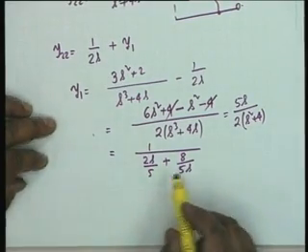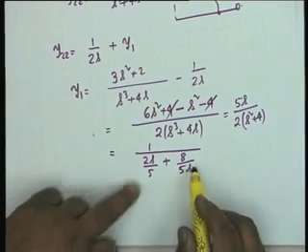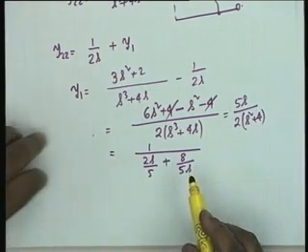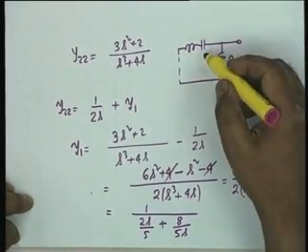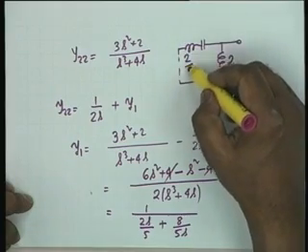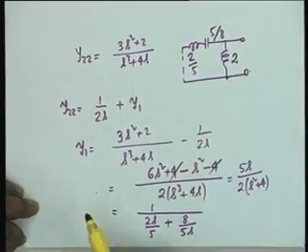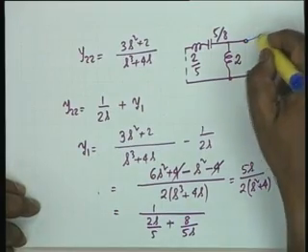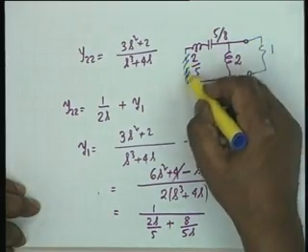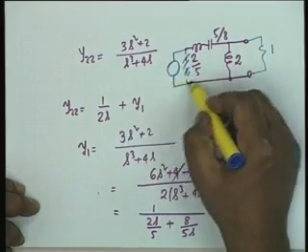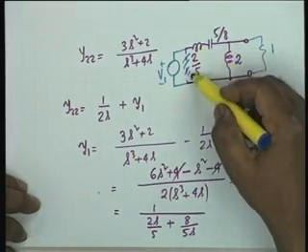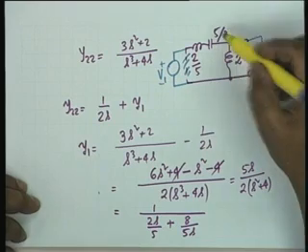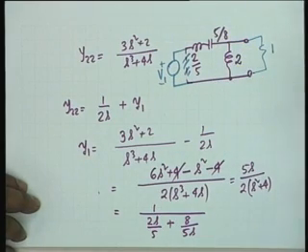Now since this is an admittance, the reciprocal should be an impedance, and obviously the other L and C are obvious now. What are they? The inductance is 2 by 5 and the capacitance is 5 by 8. So the total network shall now be: add this resistance 1 ohm, remove this short circuit and add the voltage generator V1. That is it. This takes care of the transmission zero at infinity, this at the origin and this at the origin. 2 transmission zeros at the origin and 1 at infinity.